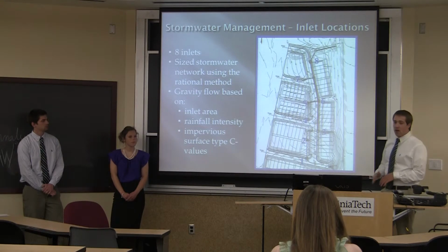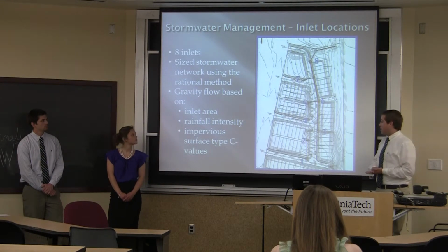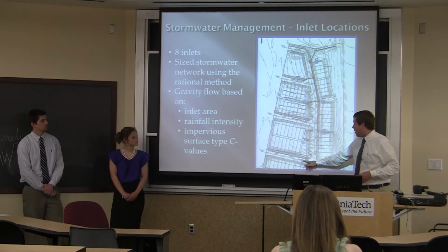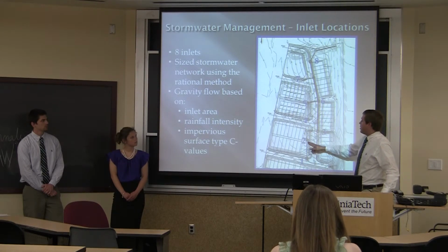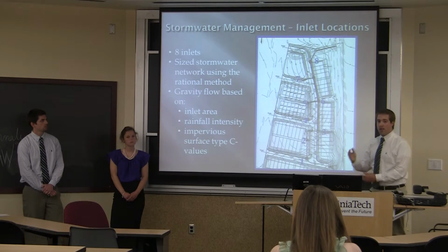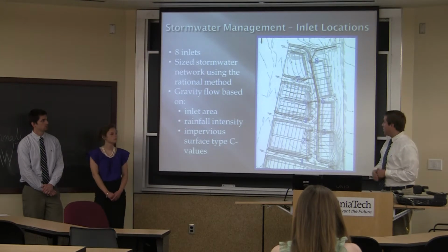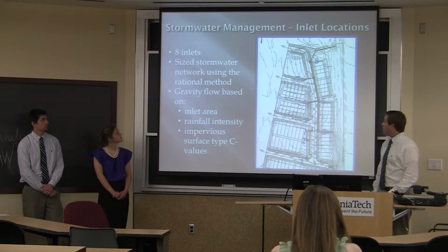And our roads are unique also because they're not crowned, they're actually sloped, so this road's sloped this way to direct the water into these specific inlets here. We also have 2 grass inlets to collect water through the ditches behind our houses. And then all that water is eventually flowing offsite.